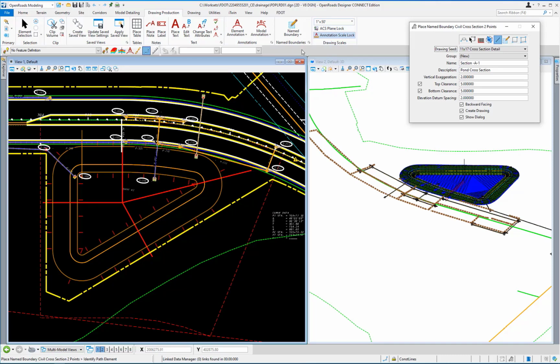Left-click on the left horizontal pattern line in View 1. The name field will change to Unnamed Cross-Section. Change the name field to Section B-. All of the rest of the fields should be set properly from the last use of this tool.